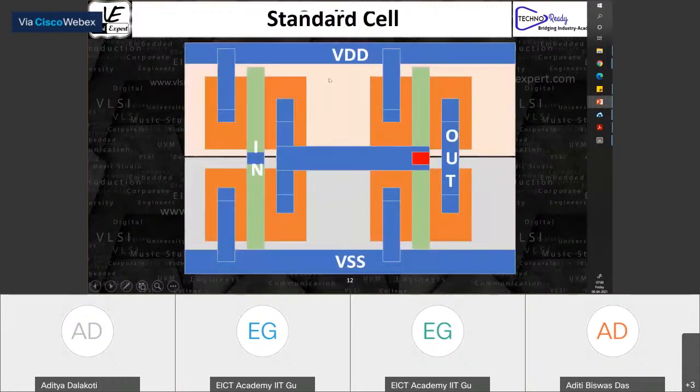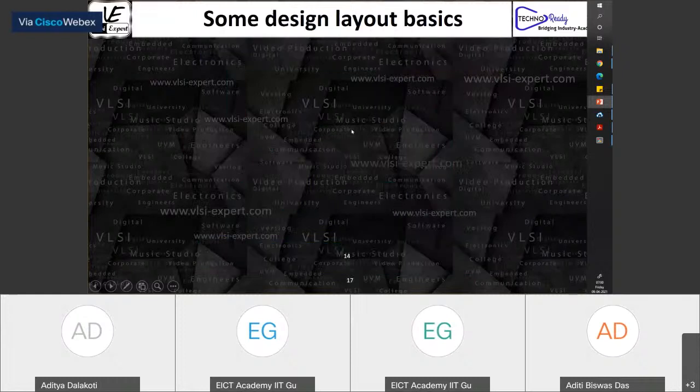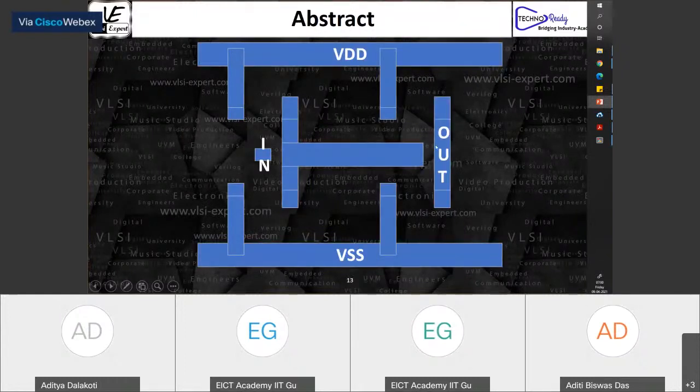So just for a refresher, we had the standard cells. This is something which we already discussed. We have abstract views of those standard cells, which guide the router on where it has to make the connections, the different ports, and the different tracks available to it. Wherever it can route different levels of metals, it is able to figure out through the LEF files of your standard cells.